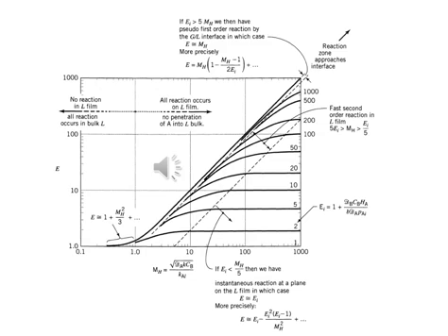So we have 3 regions. We have this region where the Hatta number is less than 1. Basically in this region, this is where we said we have case H, where the reaction has not enhanced the rate of reaction. So basically our E is equal to 1.